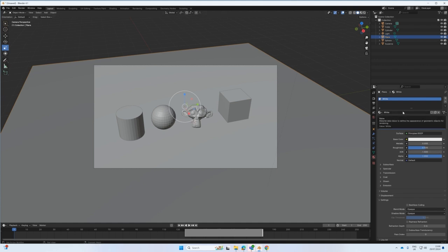Let's just create a few other ones. Your tendency is to click that plus button. But I'm going to click here. I'm going to explain that later. So here is the add a new material. So I'm going to add a new one. By default, it just adds a number. I don't want it to be called white 001. I'm going to put red. Okay. And now I'm going to click here and I'm going to choose red. Maybe that red. Okay. Create another one.